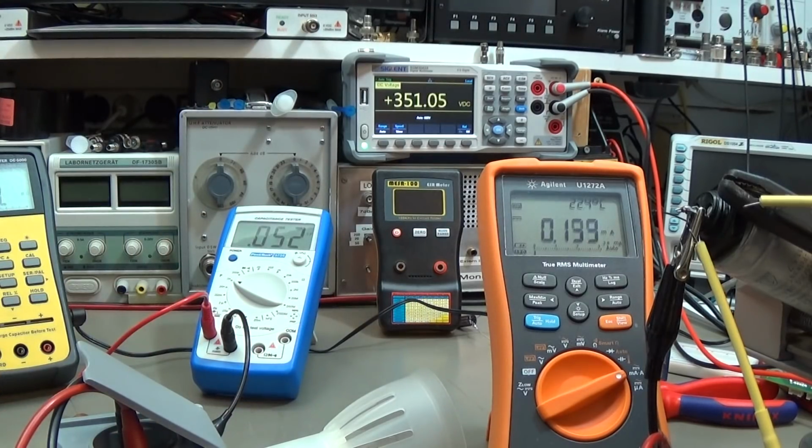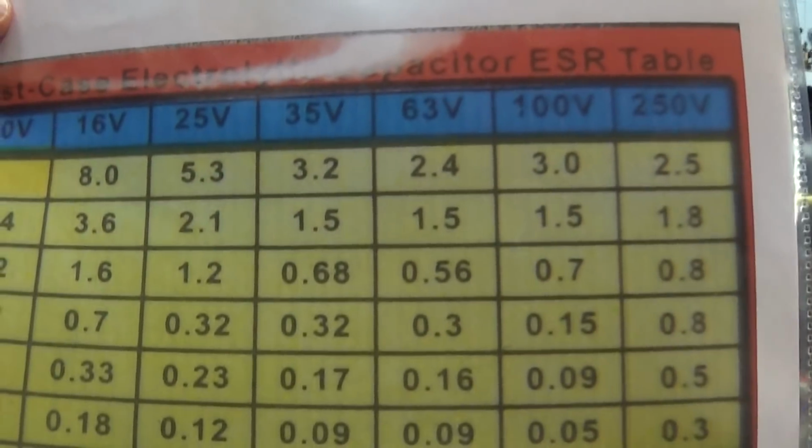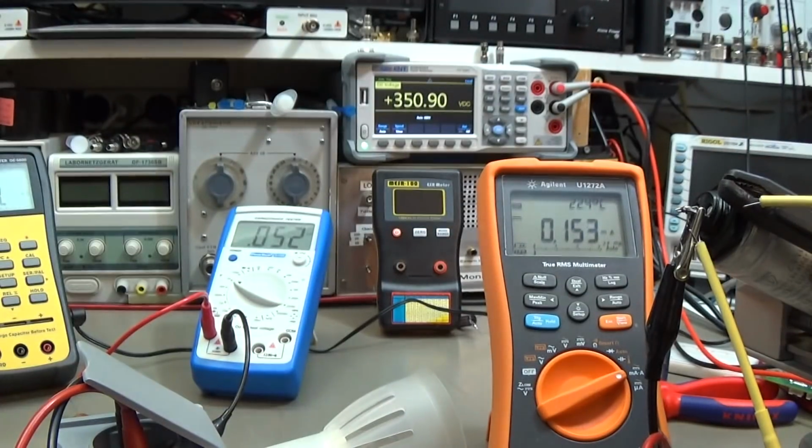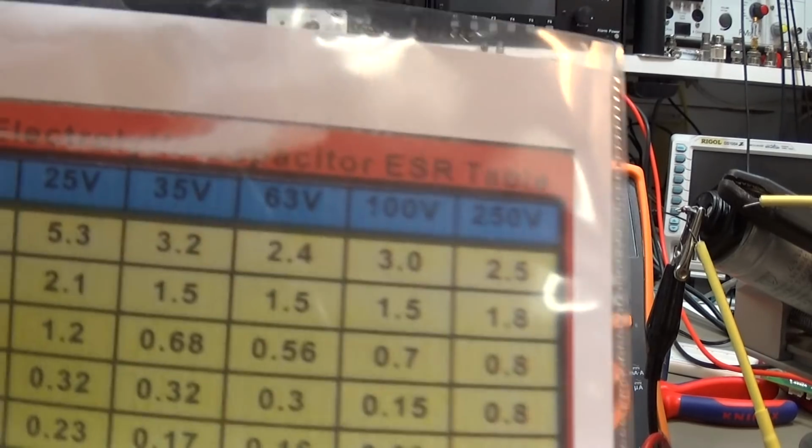So we know that if we find a capacitor with a high ESR, or even when we see it is just creeping over a level indicated in a table like this, and once again, this is a general table. The tables from our manufacturers are more accurate, and they show lower ESR values.